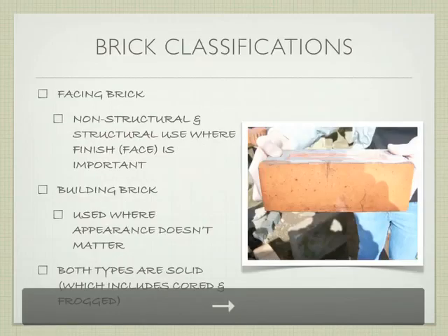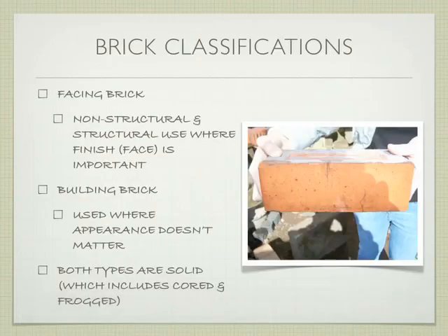Oh, the other thing I should say is obviously the larger the brick or the longer the brick, the fewer joints there are, the less labor is involved in making the building, the cheaper the building becomes, right? So there are certainly advantages to picking a bigger brick.